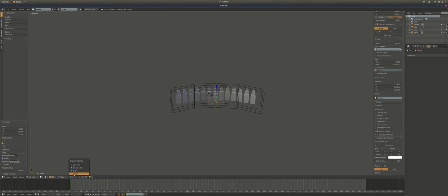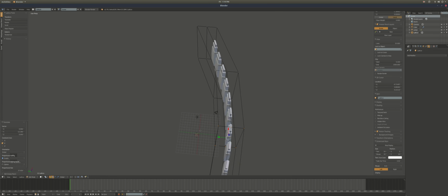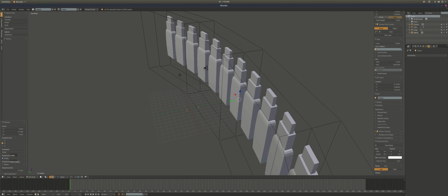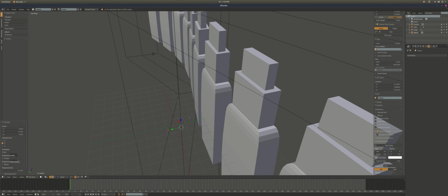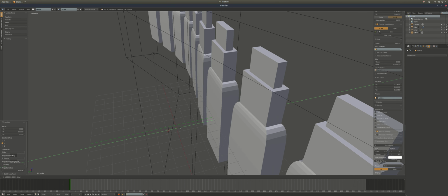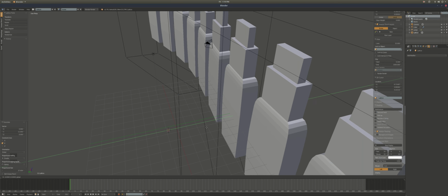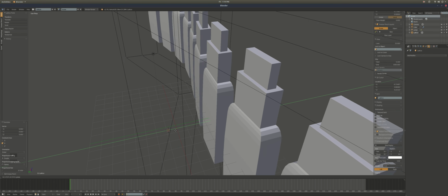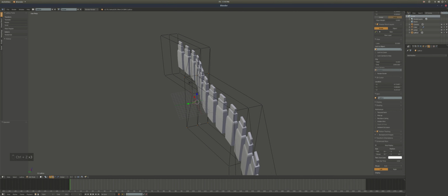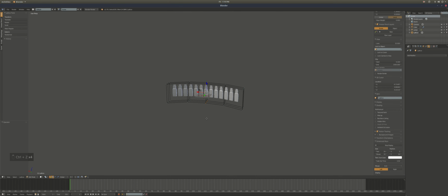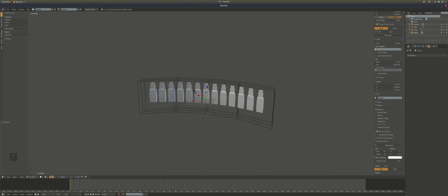And proportional editing is very useful. So is something like snap, which I think by default is snap to grid. I don't know if you can see. Yeah, there we go. Whereas if you don't have snap on, it's a free movement. It's really smooth. But you can come up with different settings for snap and use it according to how you want.